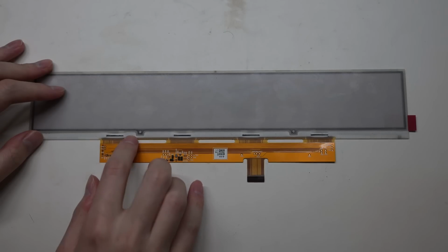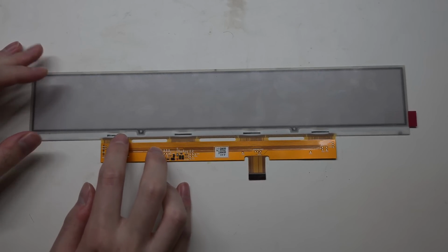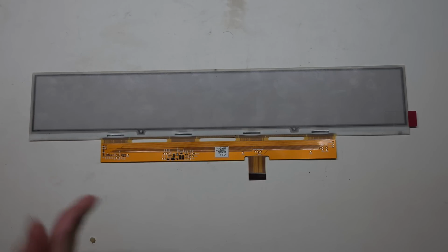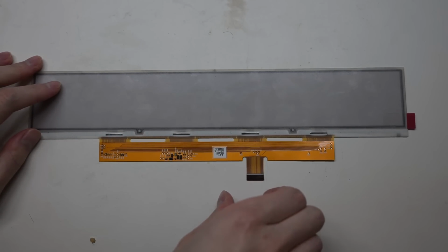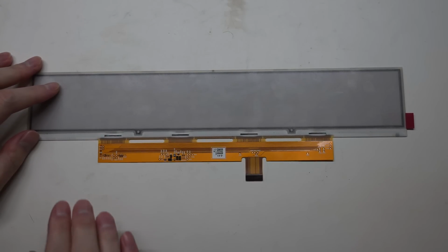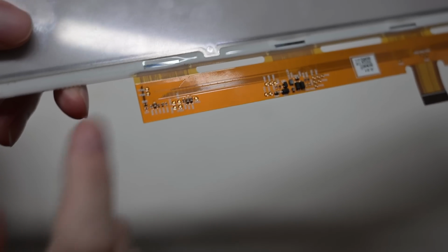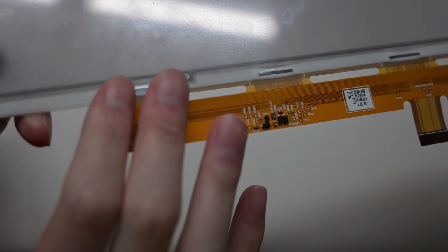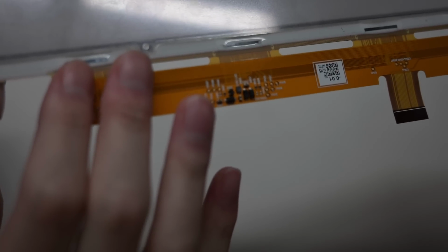Let's get back to the problem of identifying this IC. So what else can I do? Well, I still have the option to brute force it, but not by connecting a microcontroller, just by looking at it. You see, this is just a bare die that's attached to the glass. If I want, I can measure the dimension of this chip fairly accurately, down to 0.2 millimeters, say.